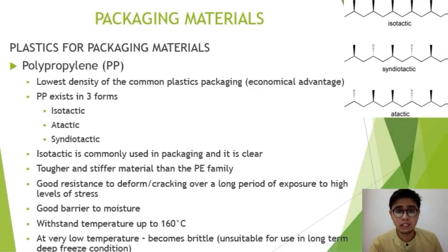Meanwhile, the syndiotactic means that the asymmetric carbons have the alternating configuration. And the last one is the atactic. It means that the asymmetric carbons have a random orientation. So the commonly used PP plastic as a packaging is isotactic because it will provide clear properties.